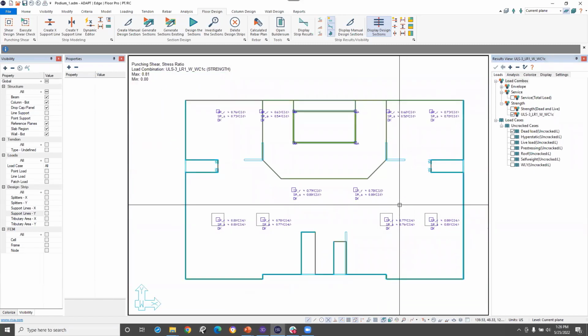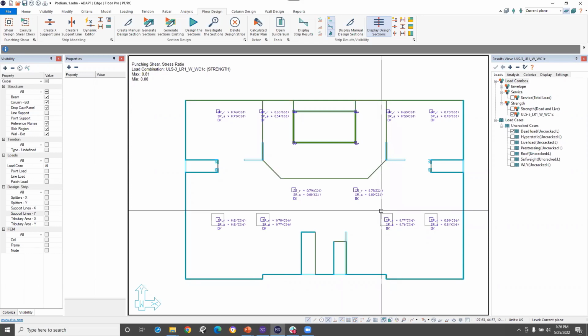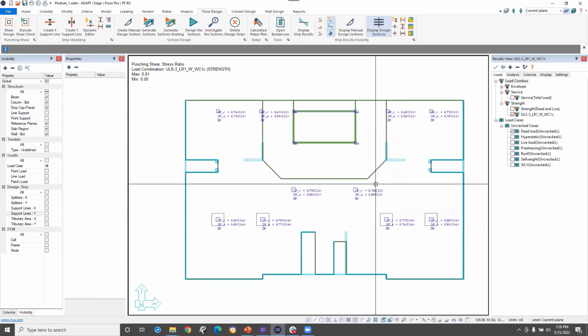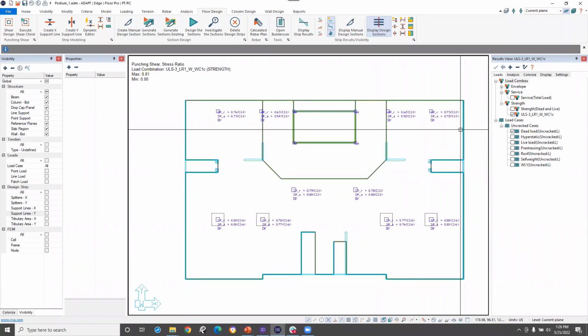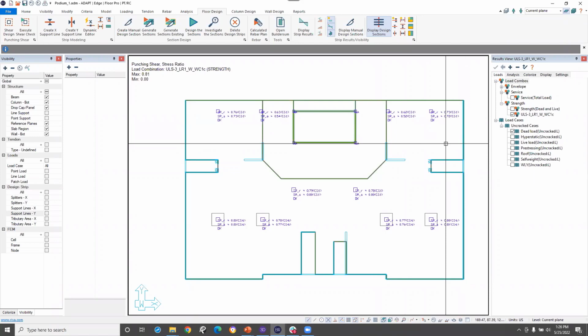So now from here, we'd probably do some massaging of the tendons, right? We had some top stresses and some bottom stresses, but really not too bad. The program did a pretty good job on picking the number of strands for our banded direction. I did a simple hand calc on targeted pre-compression for our banded direction and just laid out the tendons. Needed to do some manipulation of the profiles, but not anything too crazy. So from there, we'd probably go about, after maybe refining the tendons, go into generating our reports and, you know,